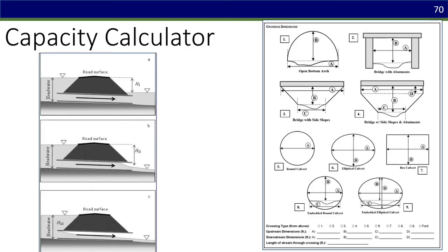So that's all hydrology, right? Trying to understand flow across the landscape to get at peak flows. Now, let's talk just a little bit about hydraulics, which is trying to get at this idea of the capacity of each culvert. The Cornell culvert model looks at just one of these approaches. We collect all of this geometry data on the right during our field assessments, and we put that into the NAC data, so we can pull that directly out of the NAC data.